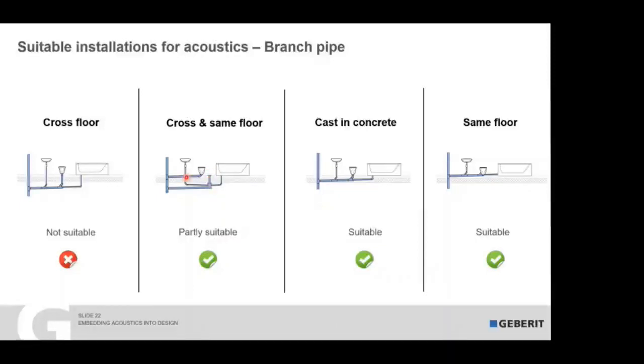and the impact of the floor drain is very low. And anyway, when the bathroom is below, there are no requirements regarding sound in the neighbor's bathroom. So whatever you do there, I would say it's not so important. It's more the neighbor's bathroom which is important. And this sound, if we can say a rough figure, is half of the toilet, and it's also not considering the diagonal room. So this is partly suitable, it depends a bit on the situation. And as Vinit said already, with thicker material we also have, of course, better acoustics.